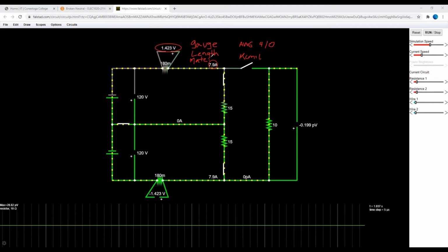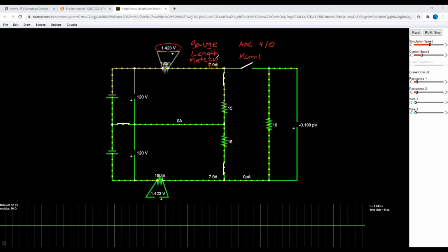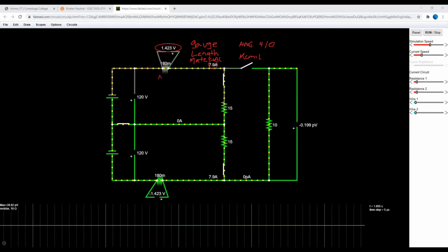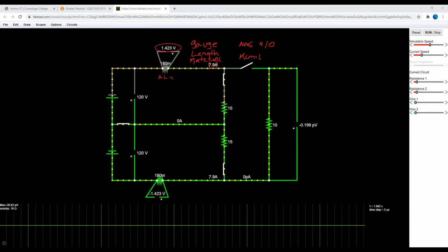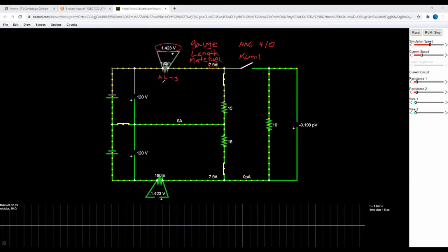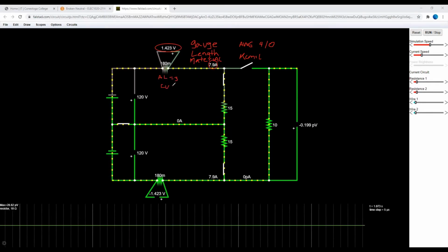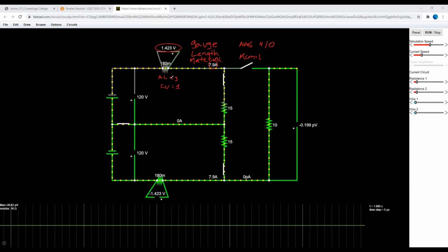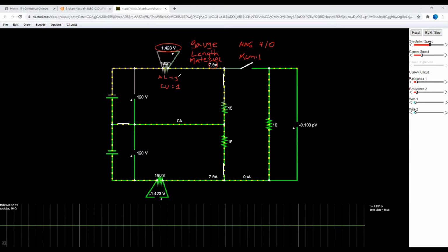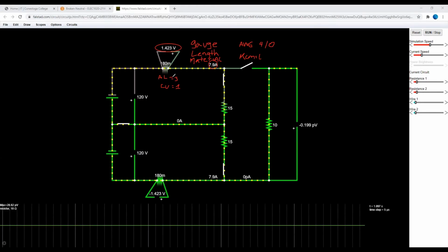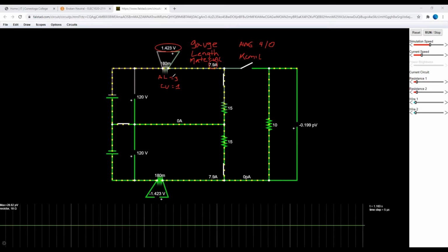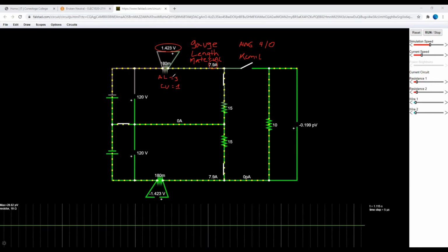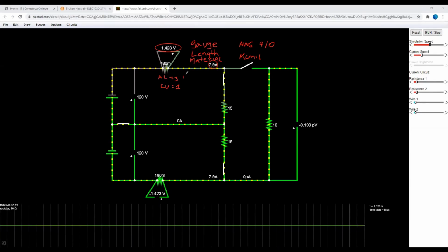For example, you can see that we covered in theory that aluminum has 3 valence electrons, while copper only has 1 valence electron. If you go to Table 1 to 4 in the code book, you would see that the minimum aluminum conductor size that we can use as per Table 1 to 4 in the code book is going to be a number 12.